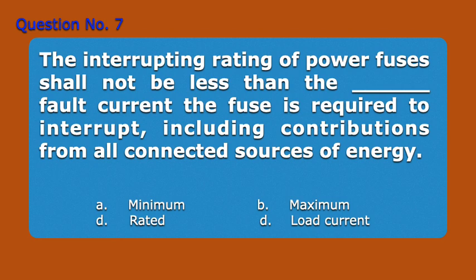Question number 7. The interrupting rating of power fuses shall not be less than the blank fault current the fuse is required to interrupt, including contributions from all connected sources of energy. A. Minimum. B. Maximum. C. Rated. D. Load current. Answer: B. Maximum.